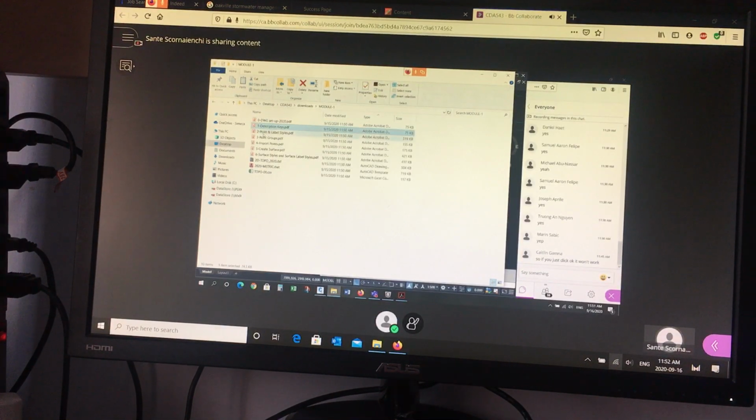So we talked about description keys, points, and point labels. Now I want to talk about point groups. So besides putting points on different layers based on their description, we can actually create groups of points. And those groups could be populated based on that description as well. So just like we put points on different layers based on the description, we could put points in different groups based on the description. And that's the next topic here, point groups.